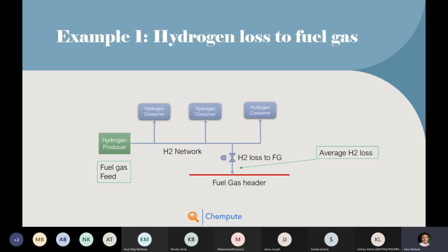The net result is that your average hydrogen loss, I would say, can be reduced by about 20 to 30%. You can quite easily do that calculation by looking at flow measurements on the hydrogen, or some way of calculating the flow. You can use that and look at 1 year of data and say, okay, on average it's so much per year, and reduce it by 20-30%, or you can use the other side, which is the production side.